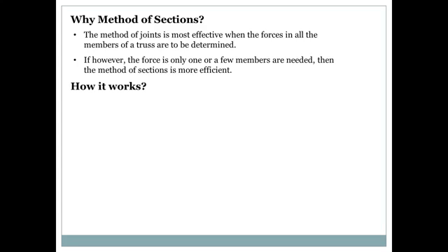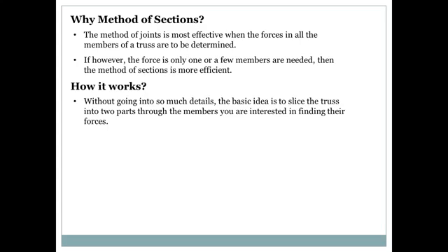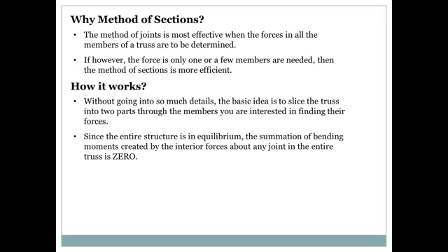Basically how it works, without going into so much detail, the basic idea is you cut the truss into two parts through the members that you are interested in finding their forces. And remember, the entire structure is in equilibrium, right?